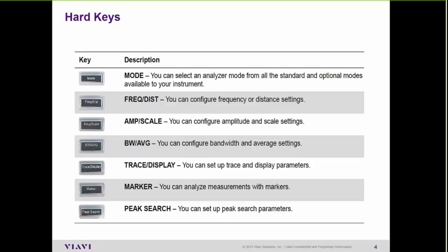So again, you can go all the way from 1 megahertz resolution bandwidth down to 1 kilohertz pretty easily under the bandwidth settings. You can also turn on video bandwidth, and you can set your averaging on this. So you can go from, say, the normal is an average of 1, so you're getting a real-time update, up to a pretty big number as far as a running average on this, and it smooths out the trace you're evaluating.